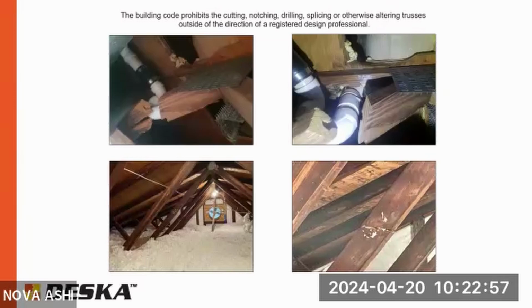All the inspector comes out to look at is to make sure that they have a certification. So they get inspected in the factory. When they get shipped, you've got your cert. All the inspector wants to see is that they're installed like they were supposed to be and they have the cert, they're good. Now, if let's say they're damaged during that delivery process or craning them in, then a professional engineer has to design a repair before they can be installed. What is